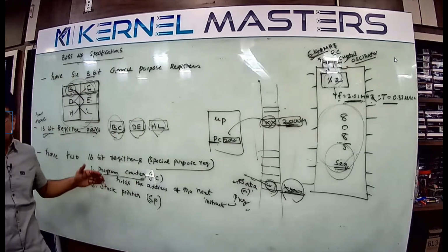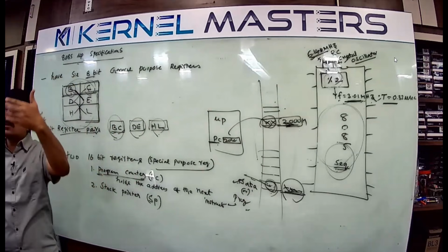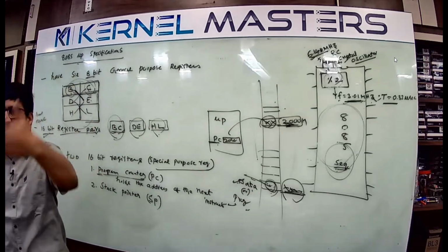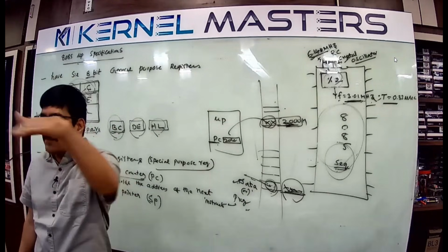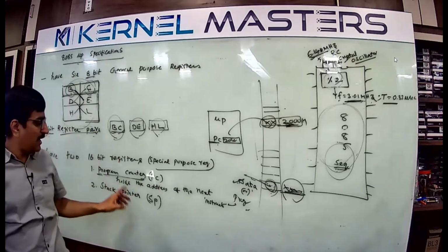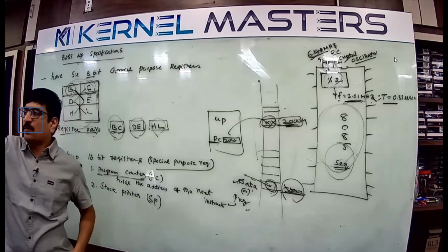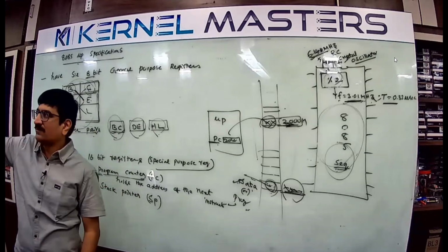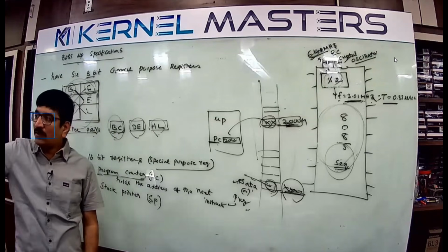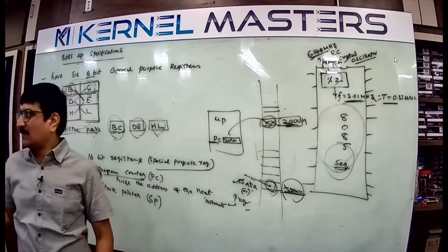Tomorrow we are going to write assembly language programs, which is important here. Tomorrow people debug the code on hardware. You should know exactly where the program stops. Who can identify that? The program counter. It identifies the line where the bug is, and you can go to that line and fix the bug. Understood?